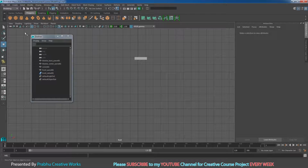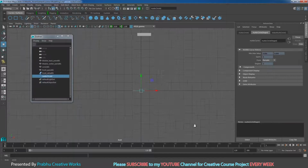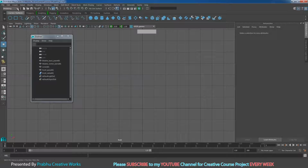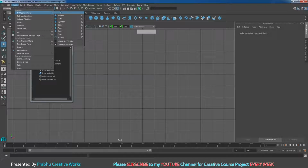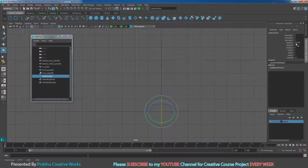So now go to curves and surfaces, click on NURBS circle. So it will automatically be created in the center of the grid. Sometimes it will not happen. So I will delete my NURBS circle. Go to create panel, NURBS primitives and disable the interactive creation in your NURBS primitive settings. So that means when you click on NURBS circle, it will automatically create at the center of the grid. Press E and rotate in X 90.